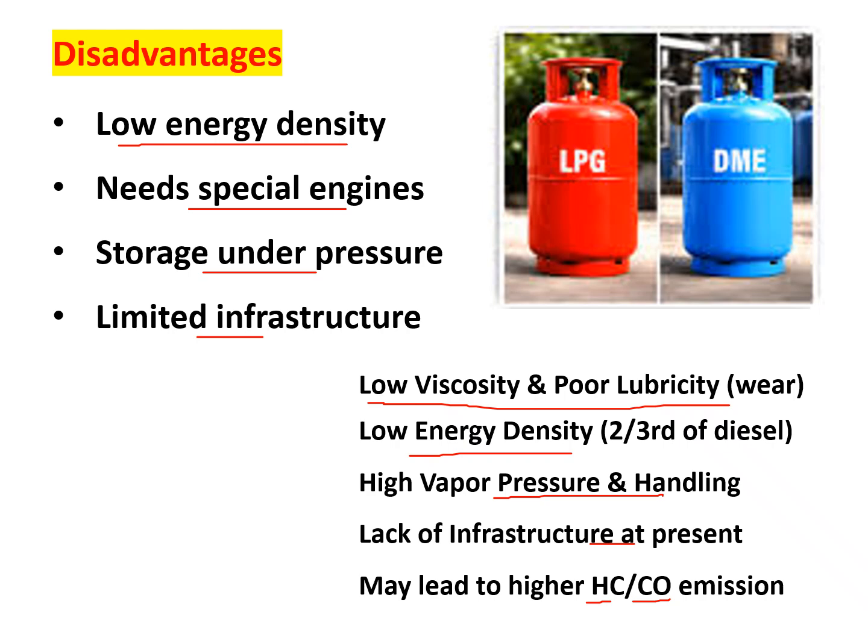We said that no pollution means no oxides of sulfur, SO2, SO3, and no oxides of nitrogen, but hydrocarbon and carbon monoxide emission may be higher, particularly if the engines are not properly designed or maintained. So these are the disadvantages of DME.